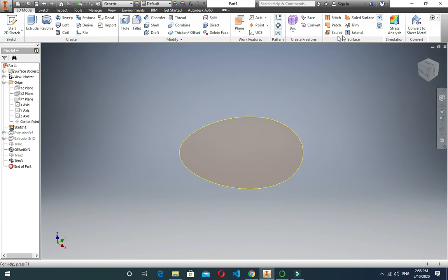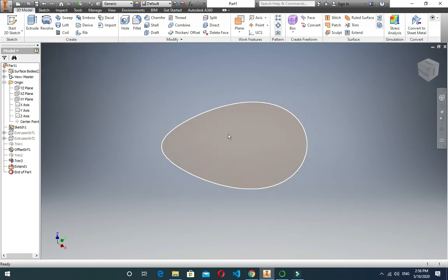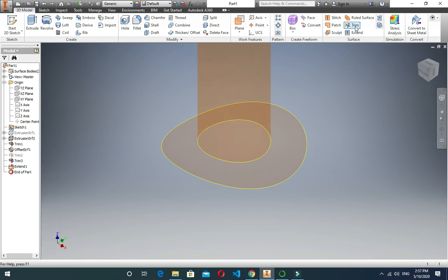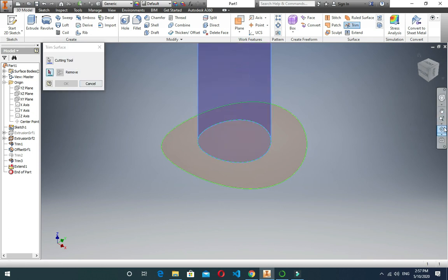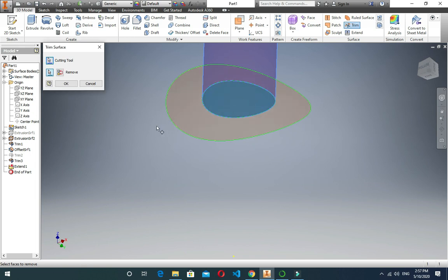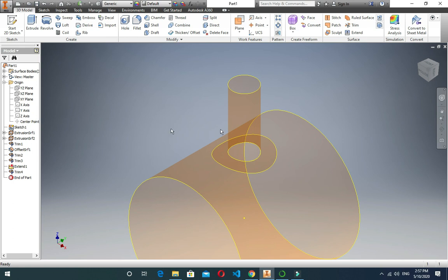Now we will extend this thing, and the amount of extension will be the width of the RPad required. So maybe I will go with 50 mm width RPad, but again we need a hole inside. For that I will switch on the connection surface, take a trim command and trim the surface which is not required. So now I have 3 surfaces, one for the shell, one for the connection, one for the RPad.